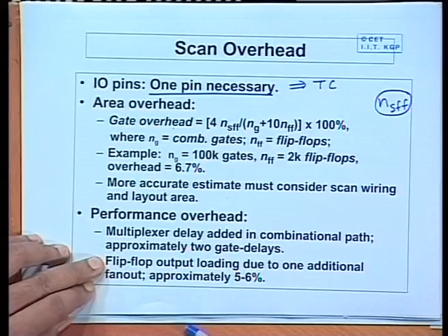So, when you increase the fan out of a gate in MOS technology, the capacitive load of the output increases. So, instead of 1, you are now driving 2 gates. So, the capacitive load becomes double. So, the charging discharging time of the output node becomes approximately double and the gate becomes slower. So, in that sense the speed of the circuit drops down.